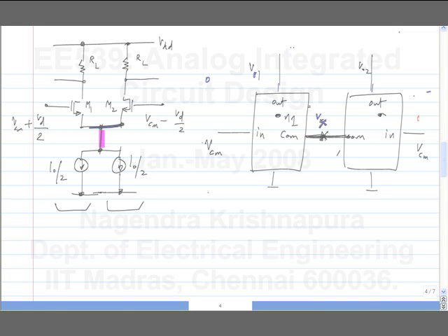Again, I run through this quickly. I have VCM and 0, I get something here, VO1A and VO2A, and I have 0 and VCM, the two will be interchanged. So I get VO2A added here and VO1A added here if I apply both simultaneously. And that is true of all of the nodes, internal nodes also. Each corresponding node will be at the same potential. It could have 100 nodes there, but you look at the corresponding nodes between the two halves, they will be at the same potential.